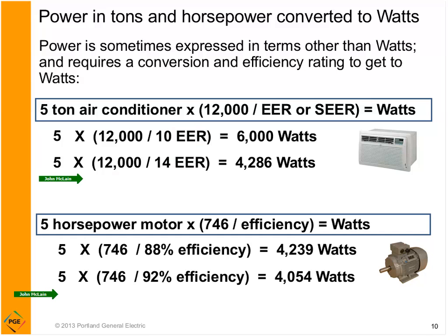Horsepower, the same thing. If you buy motors, most of them now are getting very, very efficient. But again, watch out for the efficiency rating. If someone offers you a really good deal on a used motor, check the efficiency rating. Again, you would lock in for 10, 15 years a higher wattage than you might be happy with. Quite often in businesses, the capital budget is split from the O&M budget. So the person who pays the electric bills doesn't have a whole lot of influence on the purchasing decision. But I highly recommend you get the two together.